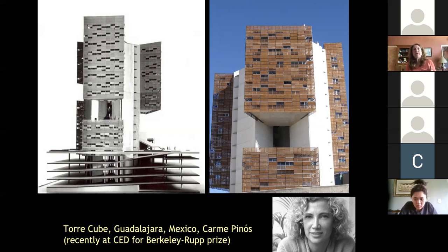And then from those main concrete shafts are cantilevered steel girders that support these trapezoidal floor slabs for the office modules. And then what you can also see, that I'll show again in the next picture, is that on a number of these stories you see these gaps, and they're omitted at various heights in each of the office wings, and it creates these breaks that allow light and natural ventilation to enter the atrium. The building relies entirely on natural ventilation in a very hot climate, and by eliminating the HVAC equipment, it also eliminates the spaces needed to house that.